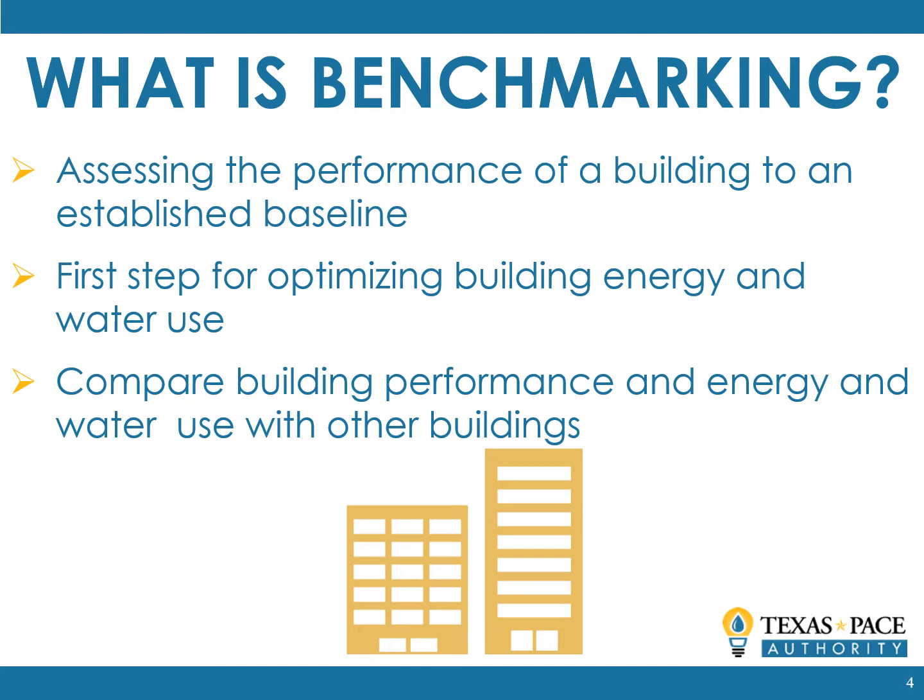Benchmarking can be used to compare facility performance over time. Because if you're not tracking your data, as we've seen earlier, you can't really improve and optimize your facility performance. Comparing your building's performance and progress to that of other similar buildings can also serve as a means of goal setting, as well as taking diagnostic measurements in terms of how efficiently your building is meeting its functional requirements relative to others.